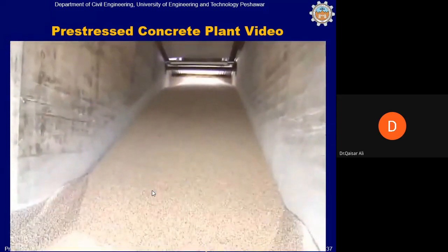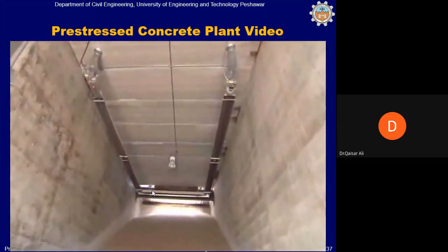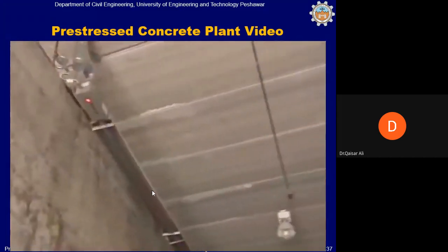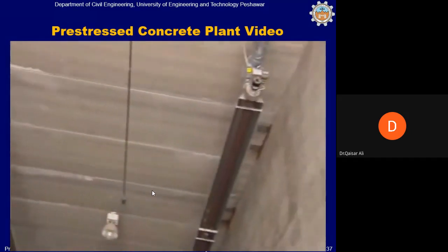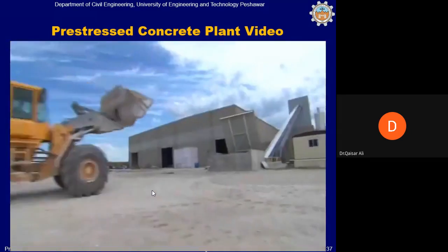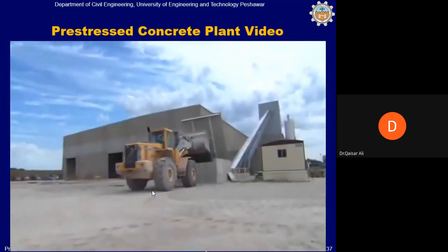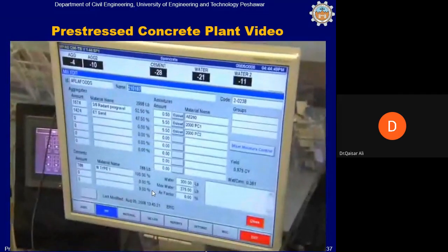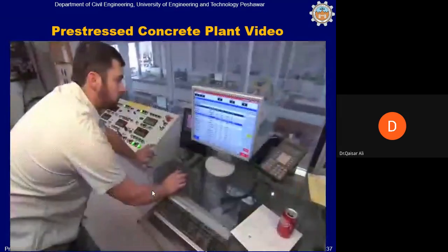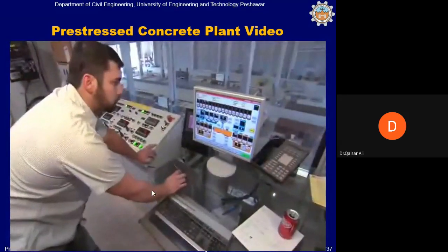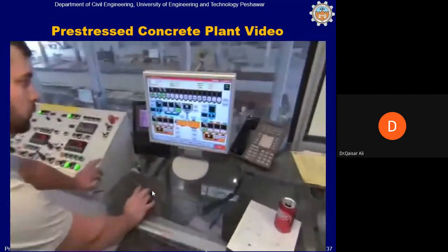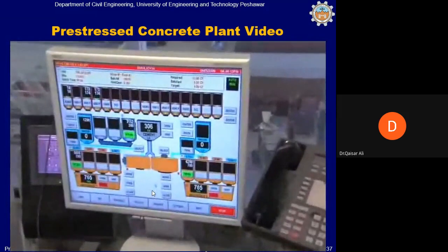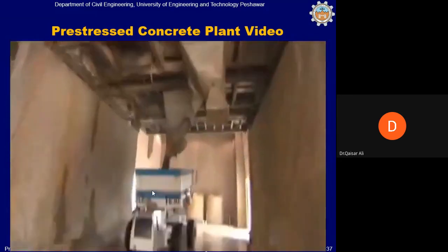During winter, in northern climates, the aggregates must be heated to get them to flow properly through the batching system and to maintain proper concrete mix temperatures. Payloaders are used to shuffle the materials to the conveyor belt. Computers are used to proportion the materials for the desired concrete mix. Cement, sand, stone, water, and admixtures are measured according to signals from the computer. After the concrete is mixed, it is discharged into a delivery device.